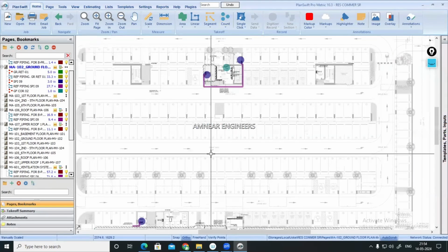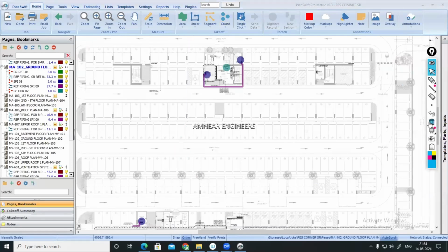See, refrigerant piping we will be pricing with respect to what? Length only. Machine we will be counting. We will be pricing with respect to the number. Duct we will be pricing with respect to the kilogram only. Or sometimes we will be pricing with respect to the square meter. Depends. As per principle of method of measurement, that should be in weight. But most of the companies in GCC, we are pricing with respect to the square meter only.